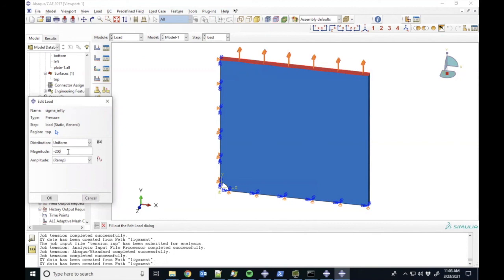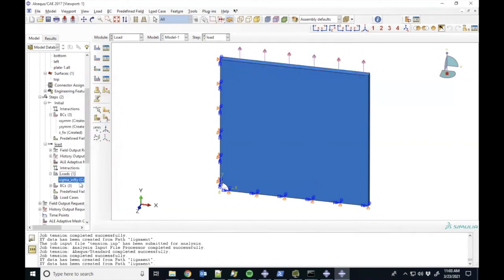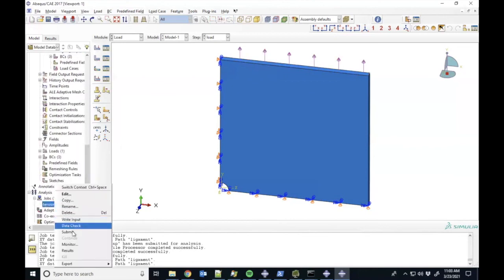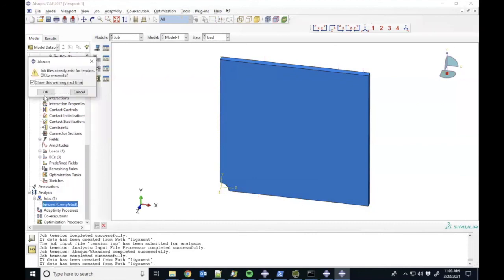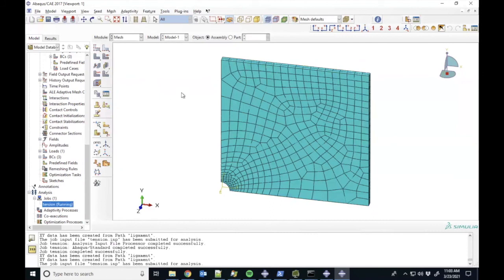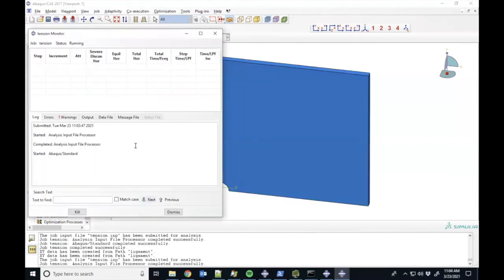Now, sigma theta theta is not the same thing as the Mises stress, but it is safe to assume here that if our sigma theta theta is 600 megapascals, the Mises stress will end up being at least greater than 300 megapascals. So we'll hit yield. And having made this increase in loading, let's rerun our job. So this is, of course, still with the biased mesh. I can show you. We're still using this mesh, which we've specialized to the steep spatial variation in stress that we expect near the hole. And it is still with quadratic elements.